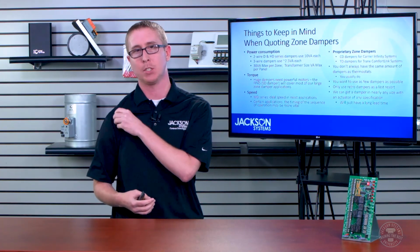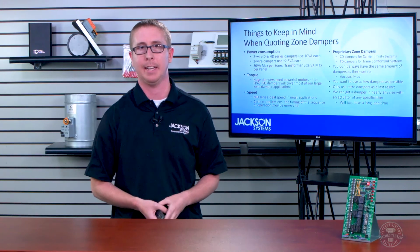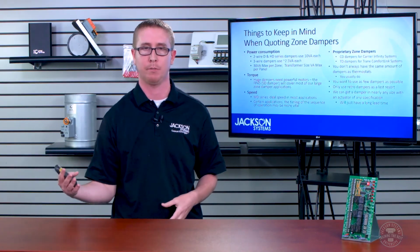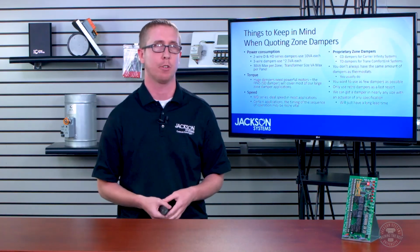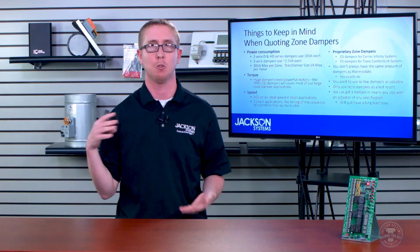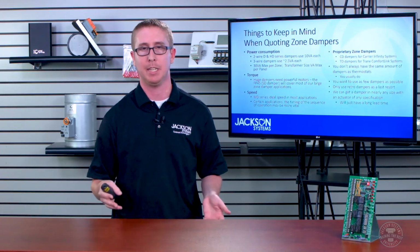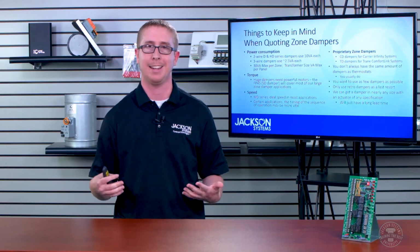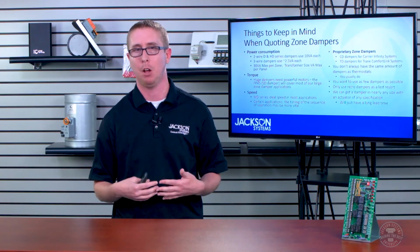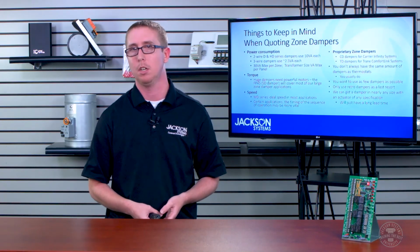We can get any actuator of any spec, though, if you were to need something that required more than 45 inch-pounds of torque. Third is speed. So in certain applications, speed's going to be super vital. In others, it's not. In general, the MD series has a 60-second stroke time. We've found that that is ideal for a large majority of the applications that we're going to run into.